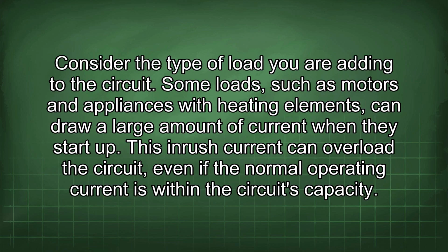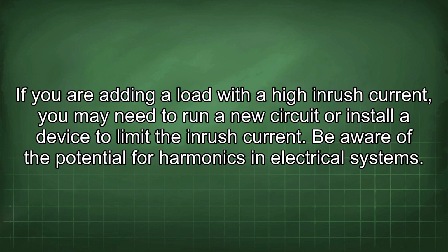Consider the type of load you are adding to the circuit. Some loads, such as motors and appliances with heating elements, can draw a large amount of current when they start up. This inrush current can overload the circuit, even if the normal operating current is within the circuit's capacity. If you are adding a load with a high inrush current, you may need to run a new circuit or install a device to limit the inrush current.